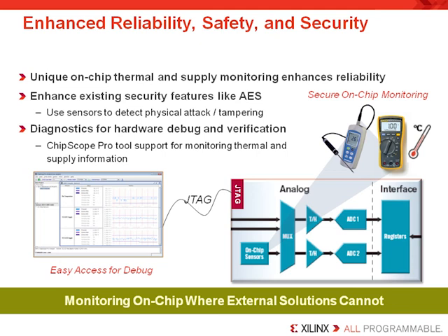Another security feature that the AMS provides is protection of the FPGA design from a hack or physical tamper of the system enclosures. This feature may be useful for aerospace and defense or even commercial customers where the FPGA is carrying encrypted or secure information and they want to protect their IP from any developed side channel attack. A side channel attack is an attempt to hack the FPGA designs by physically manipulating the system through temperature and power supply. Now, designers can prevent such side channel attacks and physical tamper of systems by using the XADC module. The XADC module can be used to detect the operating conditions outside and put the system in a mode that it becomes less vulnerable to hack.